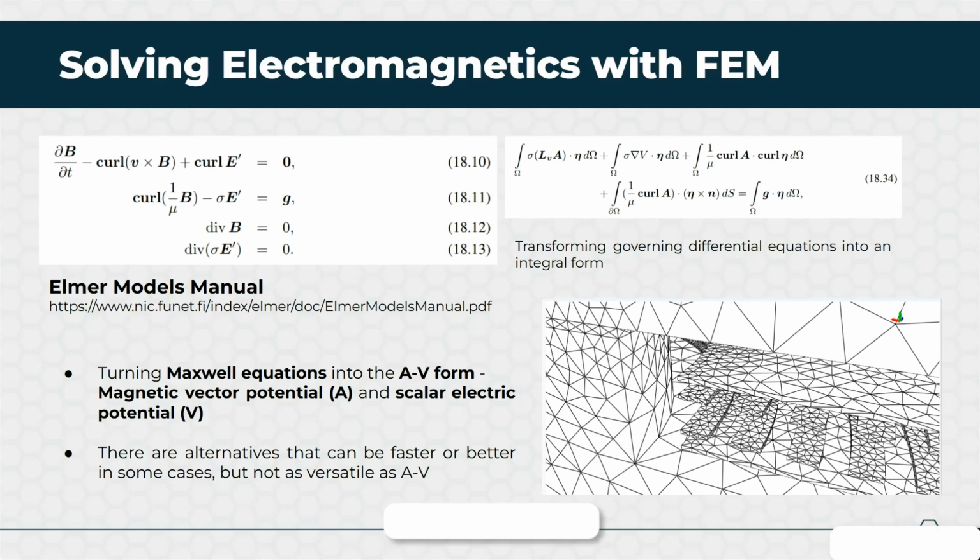In order to make them suitable for 3D FEM, we need to describe the Maxwell equations in the weak form, the form that can be solved by applying integration operations. In very simple words, in 3D FEM electromagnetics we have a computational mesh that consists of a lot of elements, and within each element we are solving an integral equation related to Maxwell's equations.